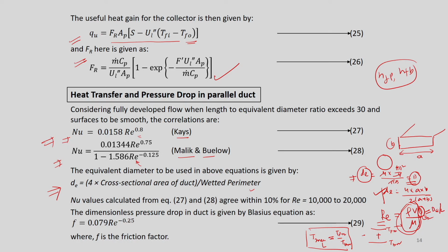And once you know that, we can substitute there and calculate the heat transfer coefficient, because the Nusselt number is known to us, h L or D equivalent by k. So from that we can calculate the heat transfer coefficient.